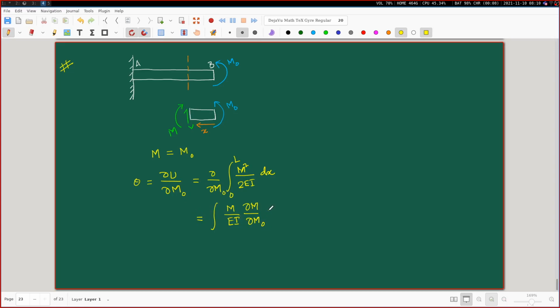Now this is just a matter of substitution. We substitute this m naught here. Del M by del m naught, what is it? Tell me. What is del M by del m naught? 1. So the answer basically comes out as m naught L by EI.